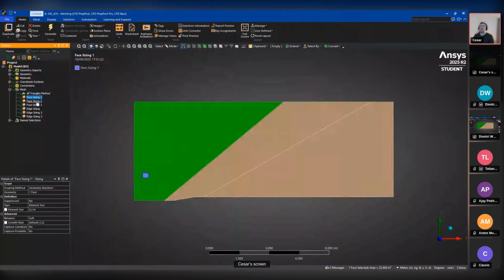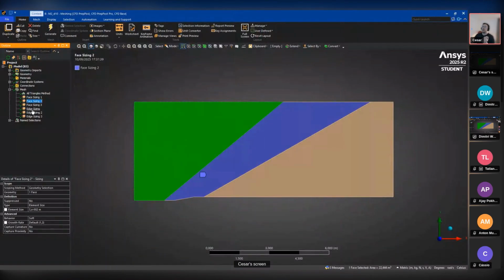And then for the methods, well, I've loaded this geometry into the ANSYS mesher, and then I've created 3 sizings, right? One for the first phase, where we don't really need a resolution because, as we already know, we're in supersonic flow, so whatever happens here won't affect upstream, right? So you don't need a lot of resolution in this area. Then we have the area where the shock occurs, right? We're here. We need a very fine resolution.